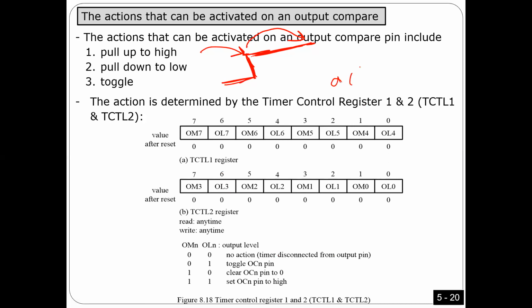So action, actually, what happens in this interrupt is that I'm going to put a number in the future, the count in the future, and then I'm going to say once TCNT, which is the counter, is equal to this future value, please trigger the interrupt and also take action on the pin. So what do you mean by action? When I explained it before, I just focused on toggle, but actually it is more than one option.